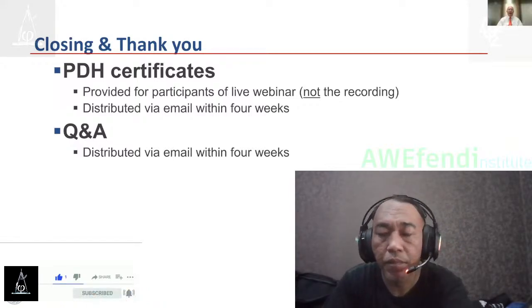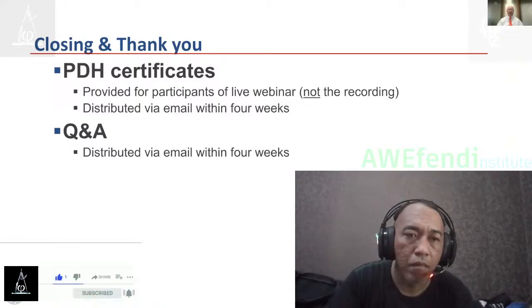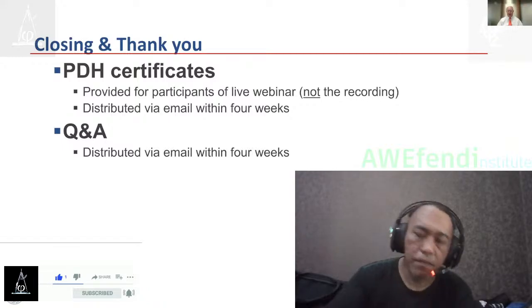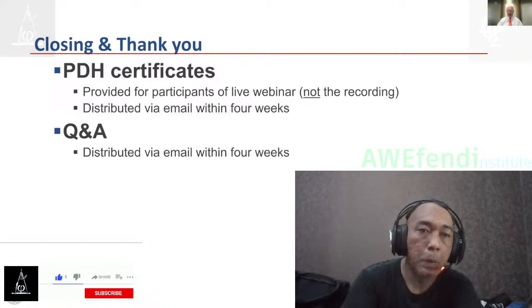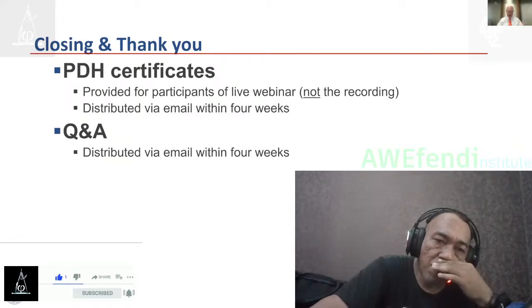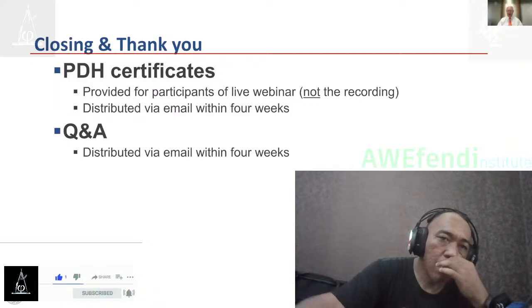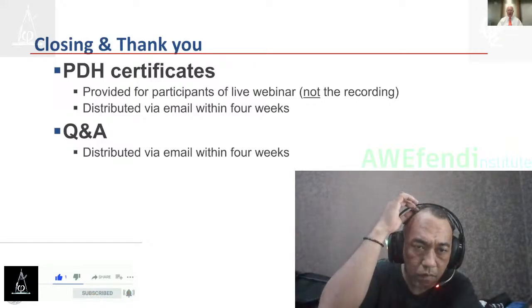Sure. So that one and another one, the triggering dimensions for the diaphragm irregularity were adjusted. And I mentioned this was not the result of lots of reentrant corner diaphragm calculations. Instead, just like the original codification, it was some judgment. I will say that the original metrics that are in ASCE 7-16 and earlier actually trace their origin to ATC 3. So the ATC 3 project, this was the ATC 3-06 project, and they number them. The ATC 3 project sought to bring us into a new world of structural engineering as related to earthquake performance.